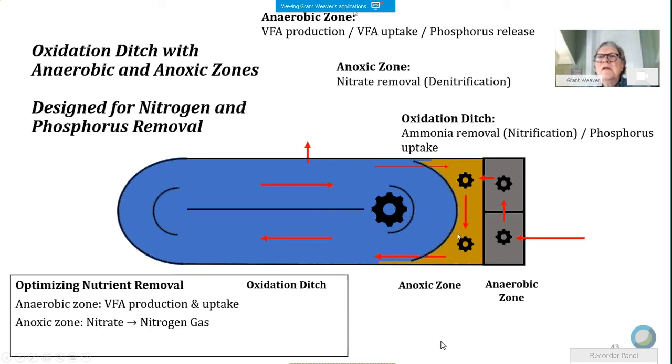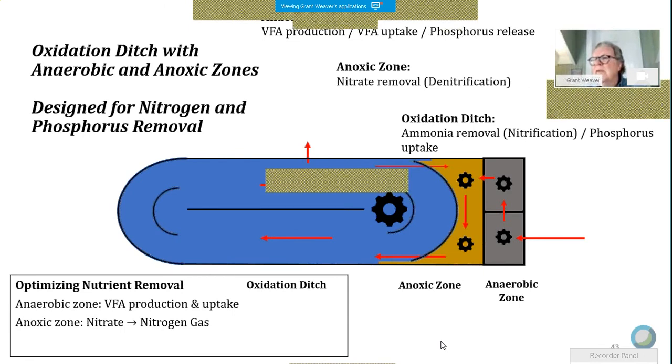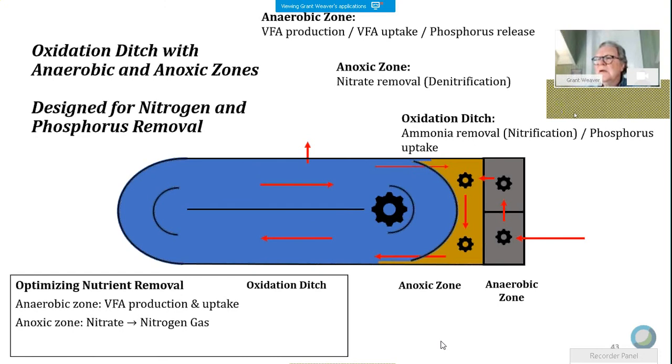And the gates are typically, let's see if I can get my little tool here. Bear with this image. I think it's going to remain over to the side there for a moment. You're going to have that little bothersome grid. But right here, there's a gate that you can open and close. If you fully open that gate, then more of this flow will go into and through this zone. You'll be bringing more nitrates in to be removed, but you potentially could be bringing so much dissolved oxygen that it could pollute this zone and reduce its ability to remove nitrates. So that's another tool.